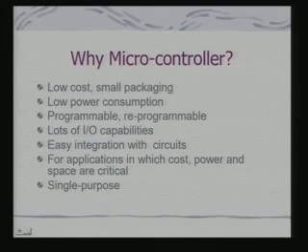And foremost, as I already stated, since I am having single purpose usage, I can manage with less sophistication on the processor hardware itself. That is why I have other peripherals integrated onto it, to get a complete system with a small footprint and smaller power consumption, and that is basically the reason why I go for a microcontroller for embedded system design.